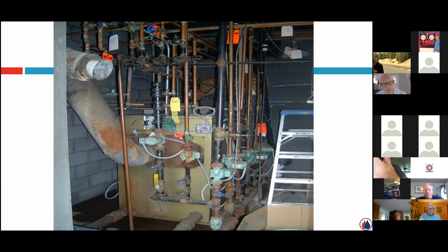All the pumps are on the return. Not sure all of the people attending this morning might have attended our fundamentals of proper pump location yesterday. But as you can see, all of the pumps, it was a pretty standard practice in the industry, especially residentially, to put the pumps on the return, which, as we spoke about yesterday, that's really not ideally the best location.